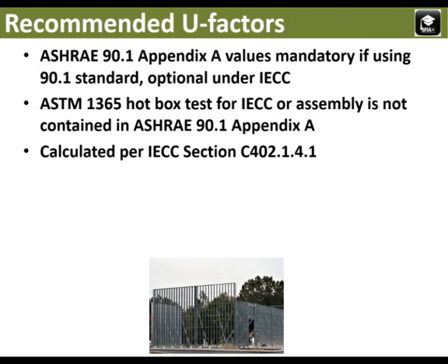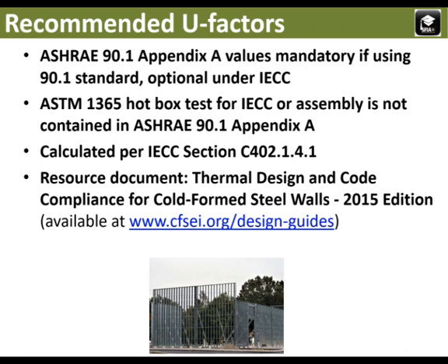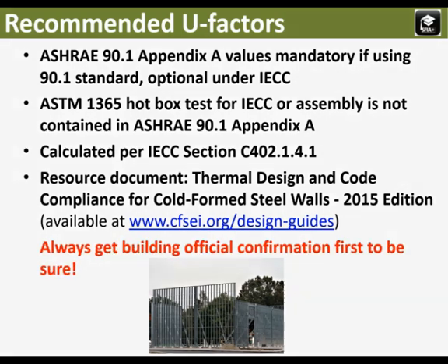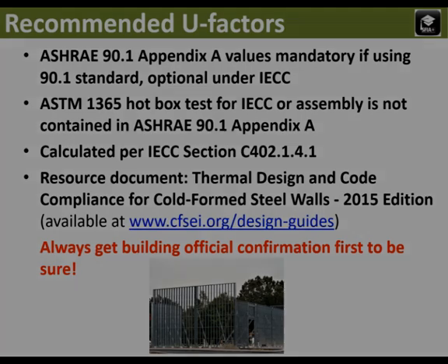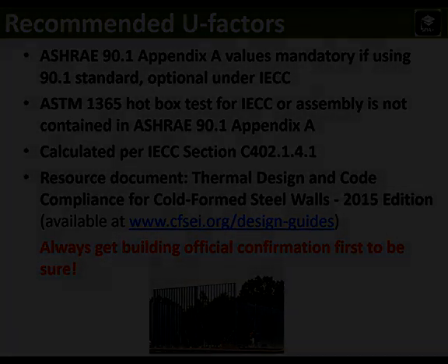Note that the industry has conducted hot box tests over the years and has published them through the Cold-Formed Steel Engineers Institute. This document also covers calculation methods. It is always wise to check with your local code official before using a specific U-factor if it doesn't come directly from the code text.